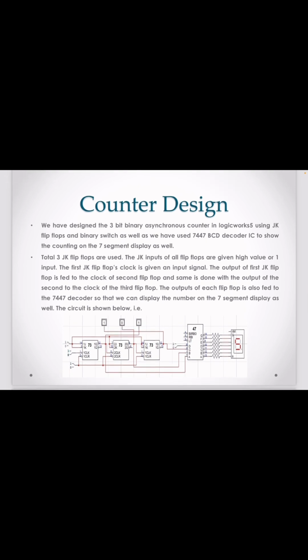We have designed a 3-bit binary asynchronous counter in Logisim using JK flip-flops and binary switch, and we have used a 7447 BCD decoder IC to show the counting on the 7-segment display as well. A total of 3 JK flip-flops are used. The JK inputs of all flip-flops are given a high value of 1.